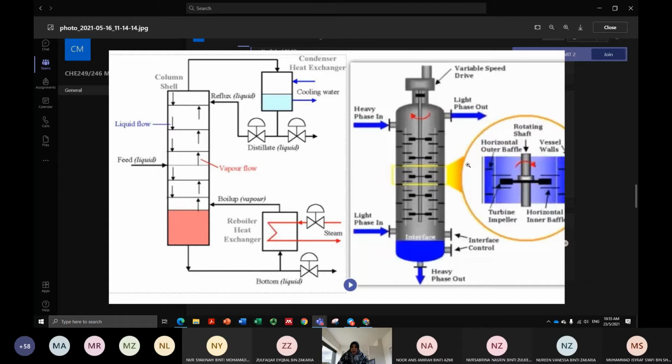Okay, and then in the last lecture, I did mention about when you have to calculate the percentage of recovery of A, or recovery of your solute. So you calculate the recovery of your solute based on what you have from the feed and then what you recovered here at your extract.